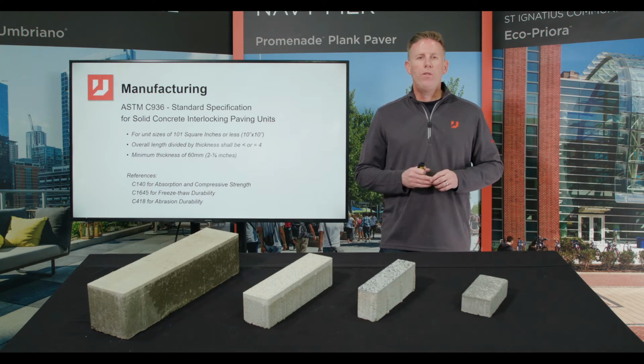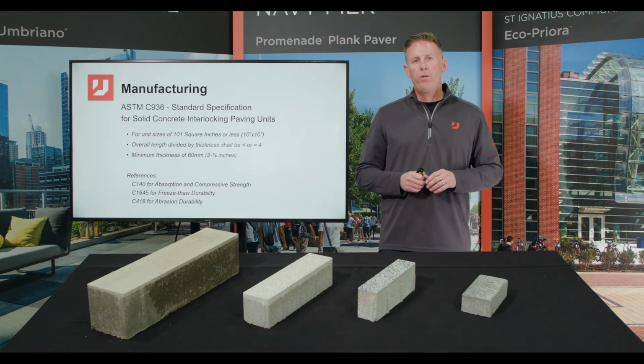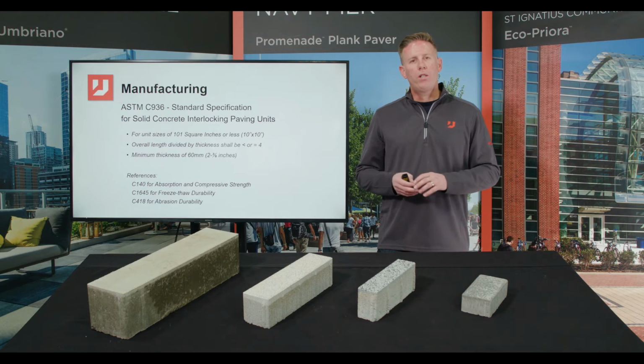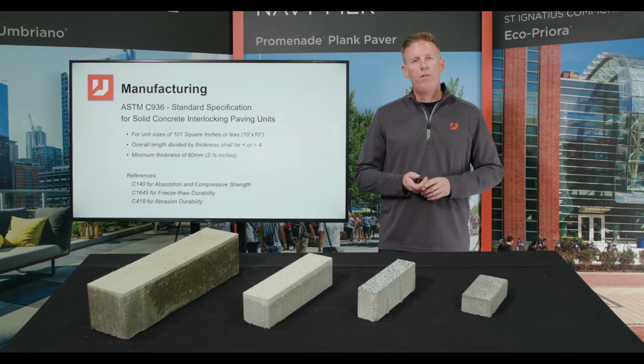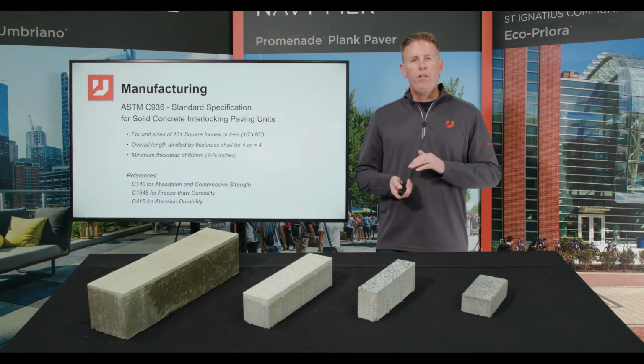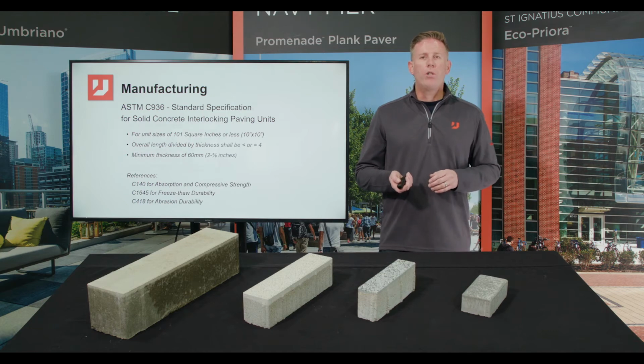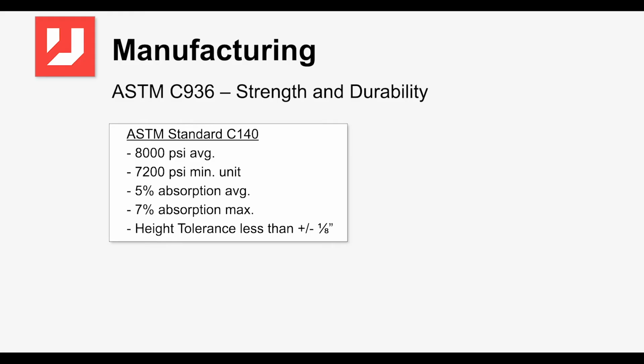The C1645 will take these pavers, we'll put it in a tank of water with about a 3% saline solution, and it can have a certain amount of dry weight loss, so it can't fracture, have pieces fall off of it. There's a maximum amount that's allowable. And then the C418 is how well that surface wears before it wears down and is no longer usable. But with the C936, the strength and durability is very evident when you look at these standards.